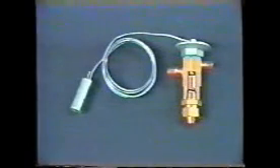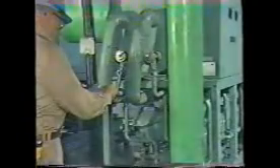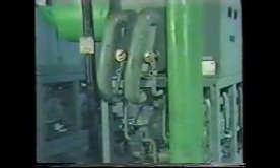Well, we've seen three different types of metering devices that can be used in refrigeration systems. First, we saw two valves, one responding to temperature and one to pressure. Then we saw a capillary tube and a float arrangement. Even though all of these devices are very different from each other, they all do the same basic job: to maintain the correct pressure in the evaporator so that the refrigerant can vaporize at a low enough temperature to absorb heat. As heat is absorbed from the area surrounding the evaporator, this area is cooled.